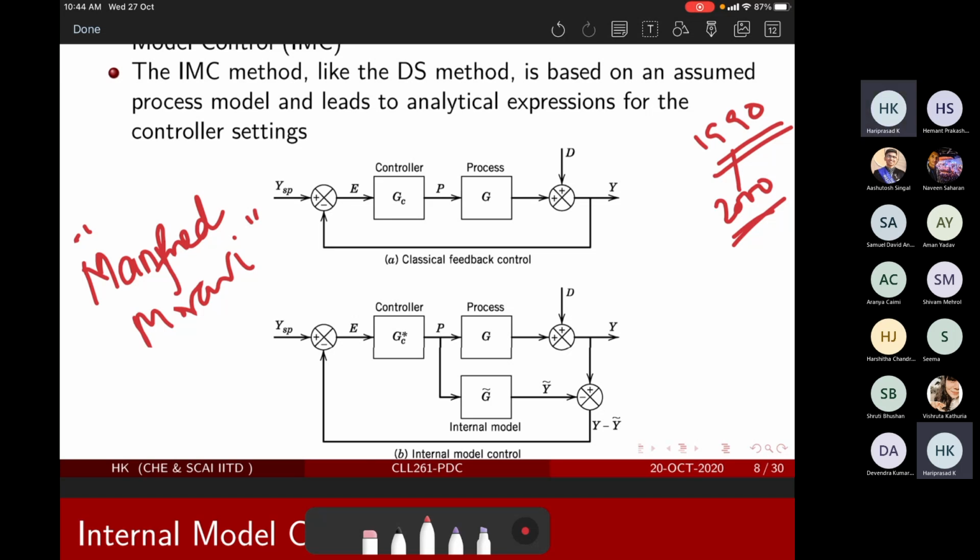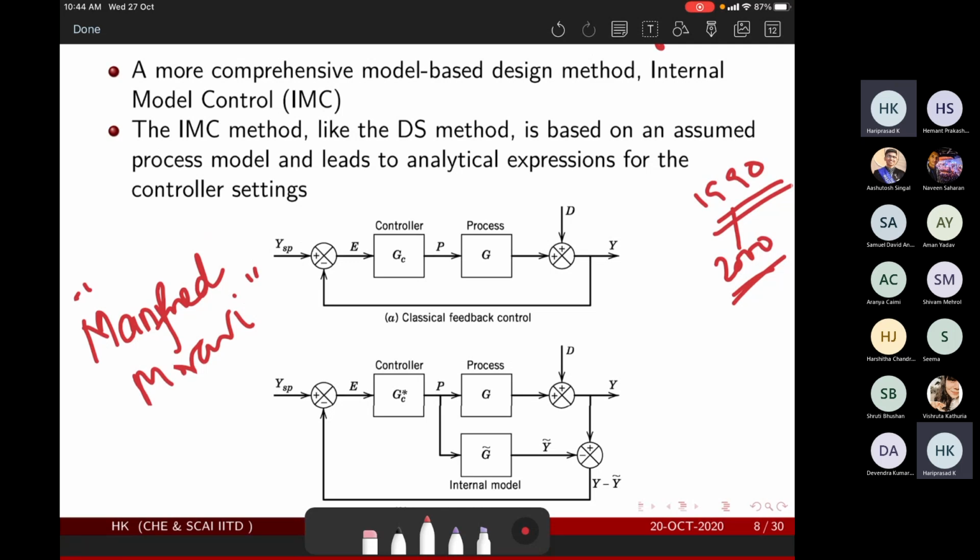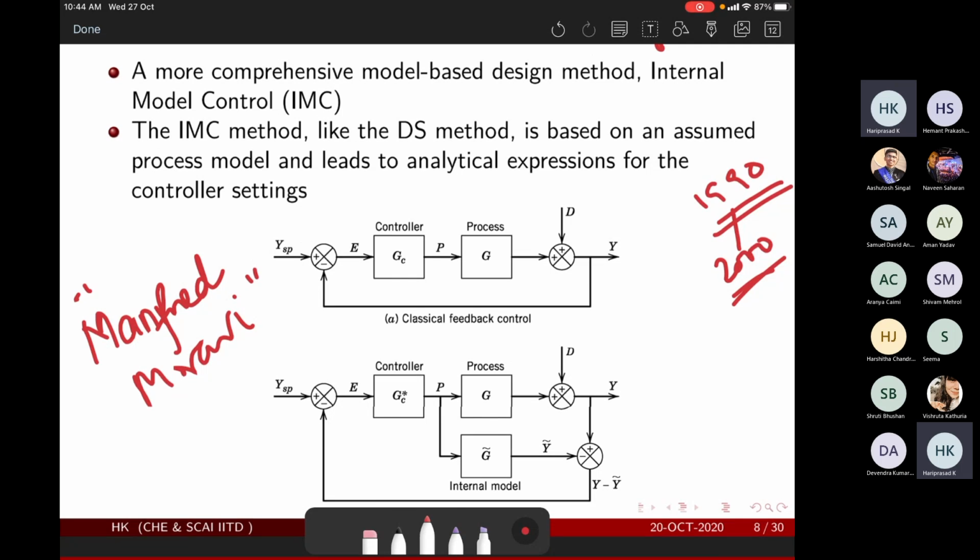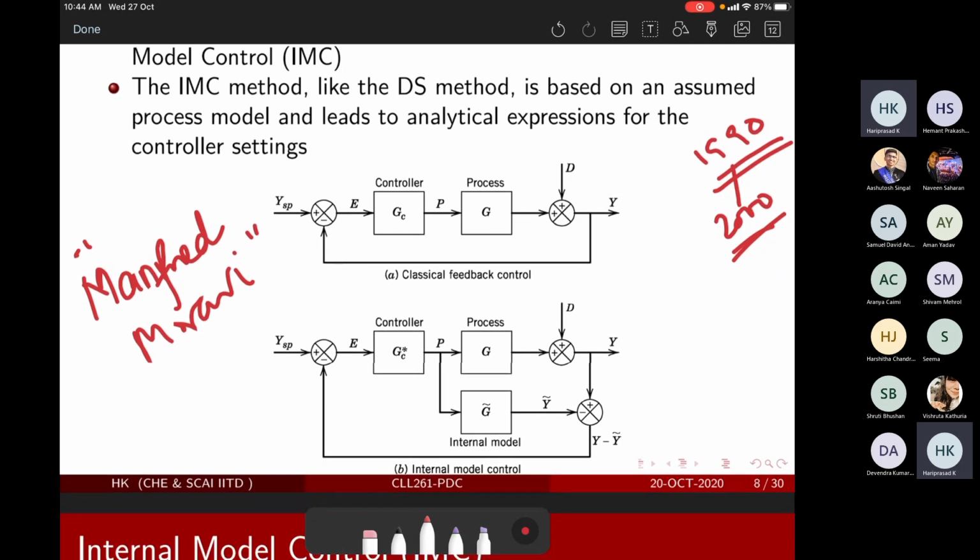It's a model based control strategy. So let's also put an internal model in the control loop artificially. This is the process model, G tilde, which is developed from data or physics, you linearize or whatsoever, and you make the control loop slightly cryptic.